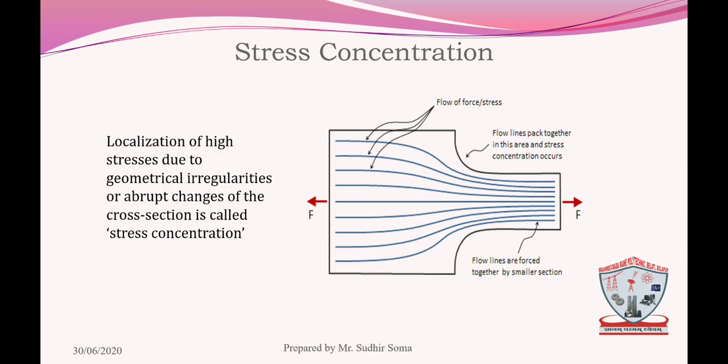There are several types of stresses acting on the element, such as tensile or compressive stress, bending, and twisting, that is torsional shear stress. Whenever a machine component changes the shape of its cross section, the stress distribution pattern no longer holds good, and near the discontinuities it is different.